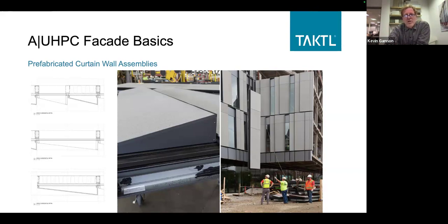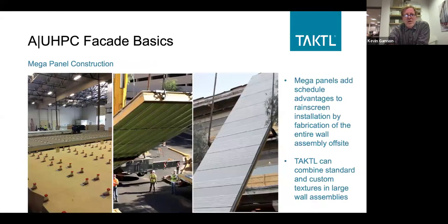We have done curtain wall projects where it is just like a ventilated cavity wall, where there is no seal of the joints. We've done some where they are dry sealed. We have done some where the joints have been fully sealed up. So there's a whole range of ways that is done. I wish I could give you standard details, but every curtain wall fabricator has their own preferences on how to go about that. So we end up working with them very closely through the design assist phase to do those projects.